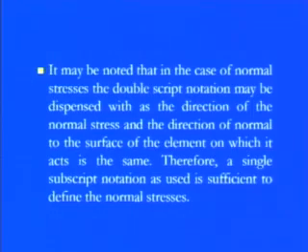Because we know that the nature of force as well as the domain have the same meaning and they are working in the same area as far as area is concerned. So here we can simply judge based on our judgment. It may be noted that in the case of normal stress, the double subscript notation may be dispensed with, since the direction of normal stress and the direction of normal to the surface of the element on which it acts are the same, as I told you, sigma xx, sigma yy, sigma zz. Therefore, a single subscript is what we are using.